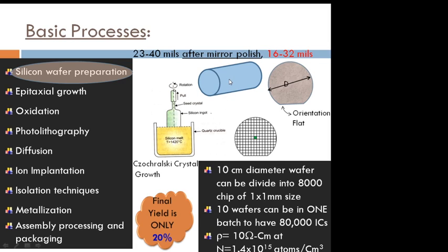So in spite of cutting with a laser, their side is not very smooth, and if it is not smooth, then naturally the growing component will have different sizes of layers. It is a variation in nanometers, but those nanometers make an impact on the accuracy of the IC, and therefore to overrule this doubt, it is always advised to do a mirror polish before using the wafer.